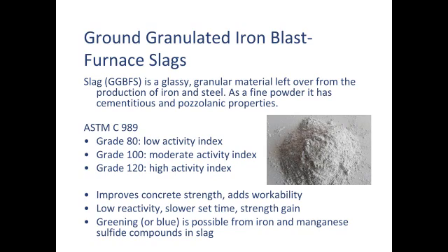Slag tends to have a lot of iron and manganese sulfides in it, and how much depends on the kind of steel and what they're making. Again, because it's just a sponge to suck all the impurities out of the steel. Well, we're using that sponge that has all those impurities in it as our pozzolan. Who knows what it is, and who knows what the steel was when we get it. So its composition can change from source to source and from time to time.